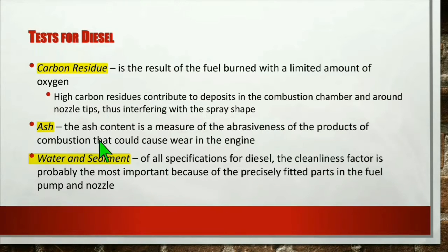Ash. The ash content is a measure of the abrasiveness of the products of combustion that could cause wear in the engine. Water and sediment. Of all specifications for diesel, the cleanliness factor is probably the most important because of the precisely fitted parts in the fuel pump and nozzle.